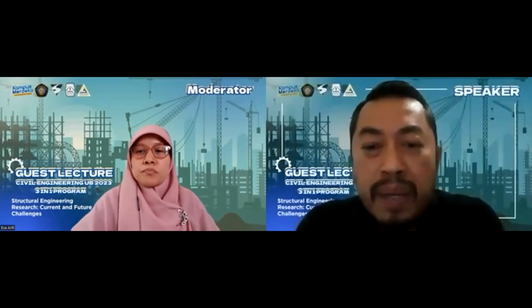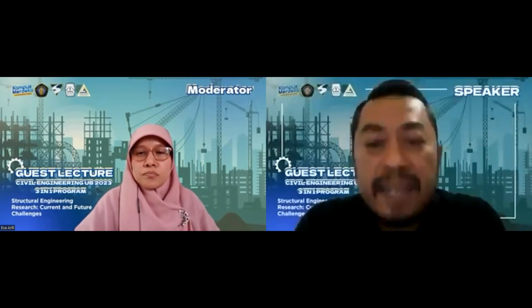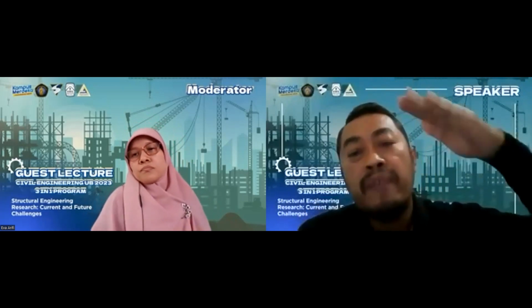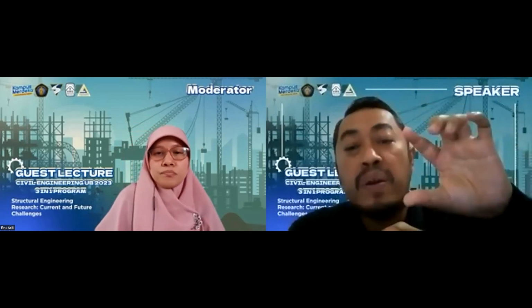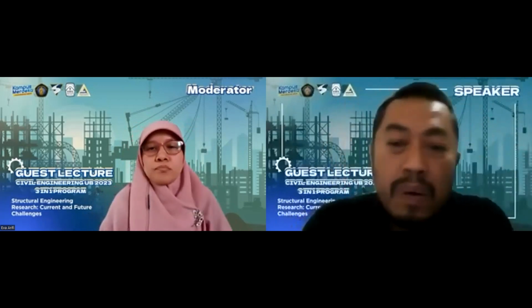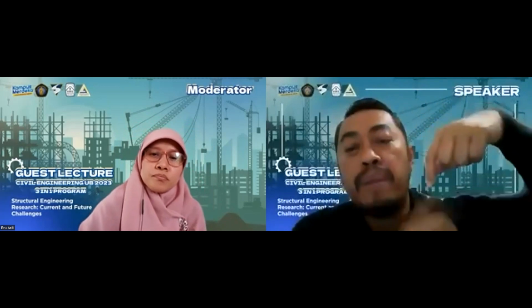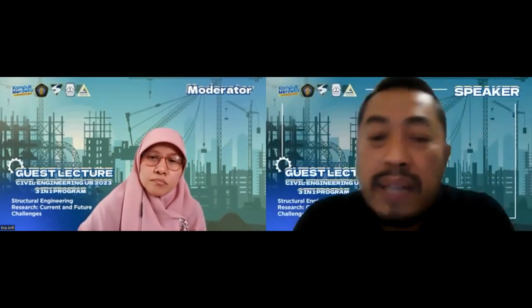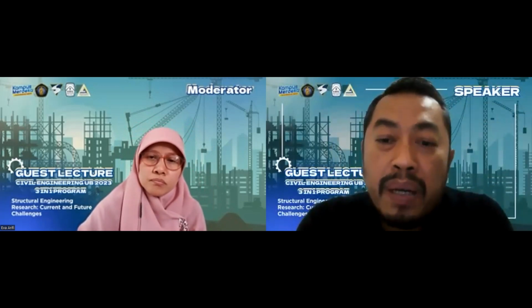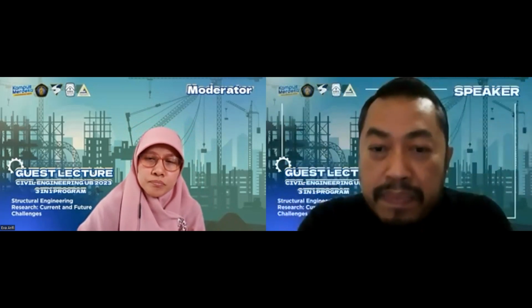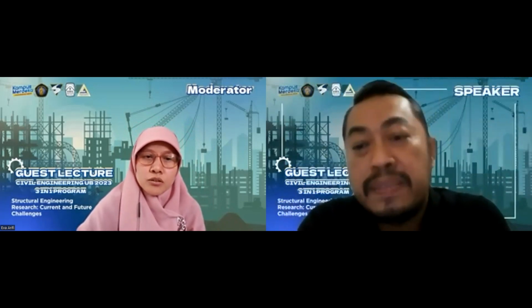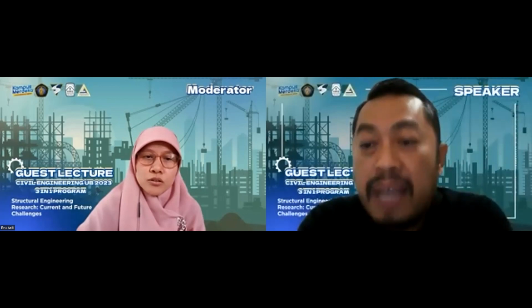But here, as I used to work as a forensic engineer, we go back to the old structure or substandard structure, let's say, where we have really bad concrete quality or very narrow stirrups or very short splices, so that we have problems when there is lateral load. So for this kind of thing we need to think about strengthening or reinforcement work or options. Like retrofit. Yeah, retrofitting.